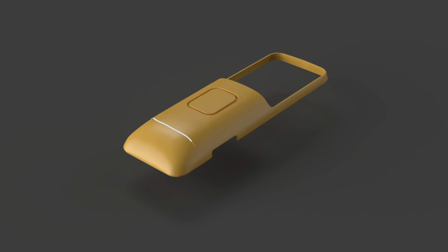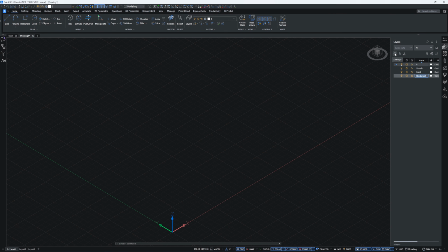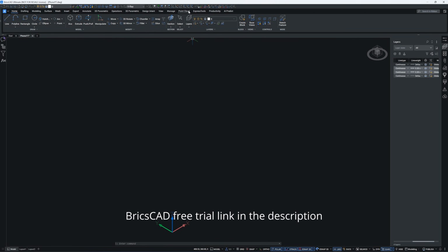Lofting along the length of an object is pretty straightforward. The real challenge is figuring out how to finish the profile smoothly at the end. When you reach the end of the profiles where the dual curved surface starts to form, you need to fan out your 2D sketches like this and build several loft sections. That way, the transition stays smooth. In this tutorial, I'll be reverse engineering the model using BricsCAD.